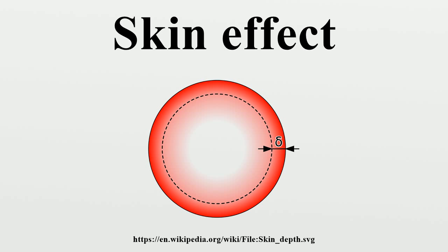Solid or tubular conductors may be silver-plated to take advantage of silver's higher conductivity. This technique is particularly used at VHF to microwave frequencies where the small skin depth requires only a very thin layer of silver, making the improvement in conductivity very cost-effective. Silver plating is similarly used on the surface of waveguides used for transmission of microwaves.